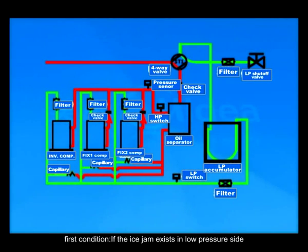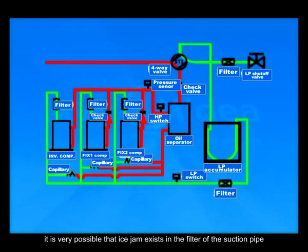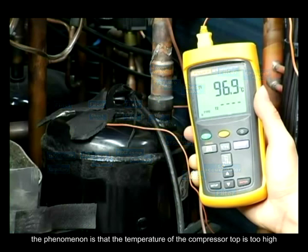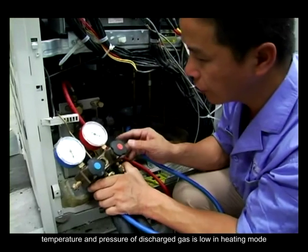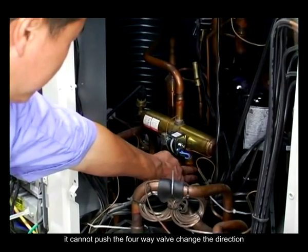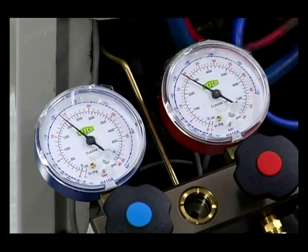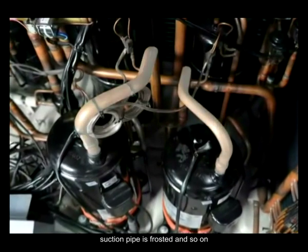First condition. If the ice jam exists in the low pressure side, it is very possible that ice jam exists in the filter of the suction pipe, capillary, or places with small diameter. The phenomenon is that the temperature of the compressor top is too high. Temperature and pressure of discharged gas is low. In heating mode, it cannot push the four-way valve to change the direction. High and low pressure of cutoff valve is similar. Suction pipe is frosted, and so on.